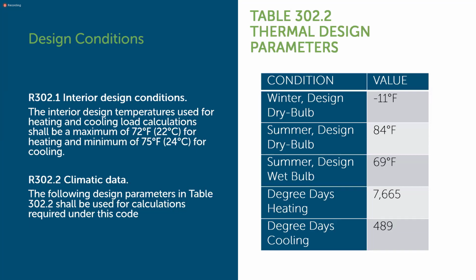If you want to get into the details, there's climate data available through local regional airports as well as other data points if you start looking online. So if you want to dial in the design temperature for a specific locality, that's certainly the best route to take. I mean, there's certainly a difference between design temperature in Brattleboro and design temperature in Jay. So these are things that certainly affect the comfort and overall energy use for equipment in buildings.